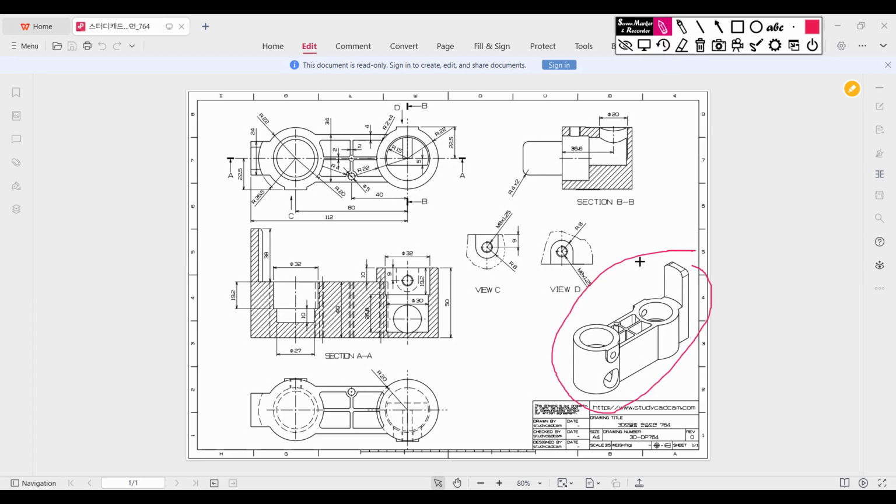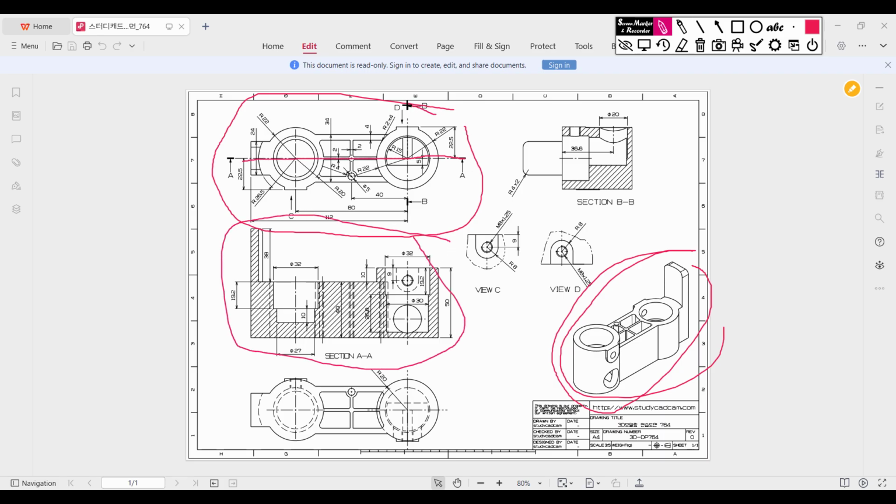In this 3D problem, this is the isometric view. Then this is our top view. In our top view, we can see a section of AA, and this section AA view is here. Then we have two portions, a section D view and a section C view, and those views are highlighted in these two portions. Along this line we have a section BB view, and this is our section BB view. For a clear understanding, this portion of our top plane is this portion, so it is rotated 180 degrees, so don't get confused.